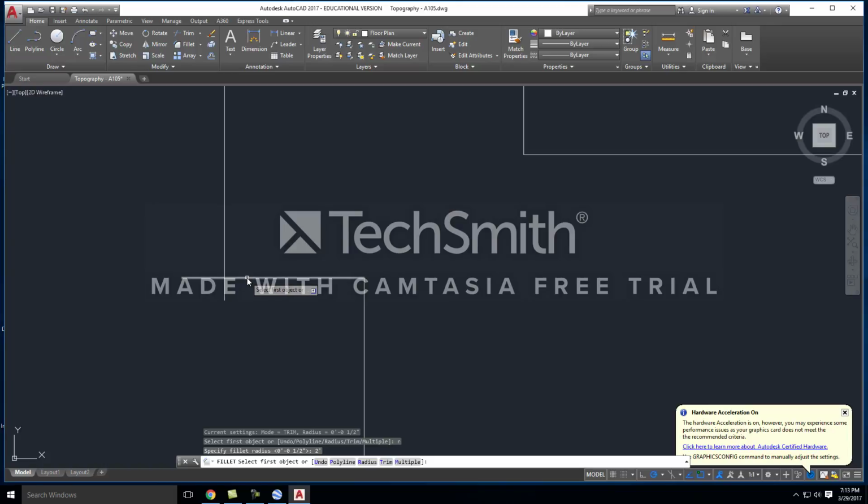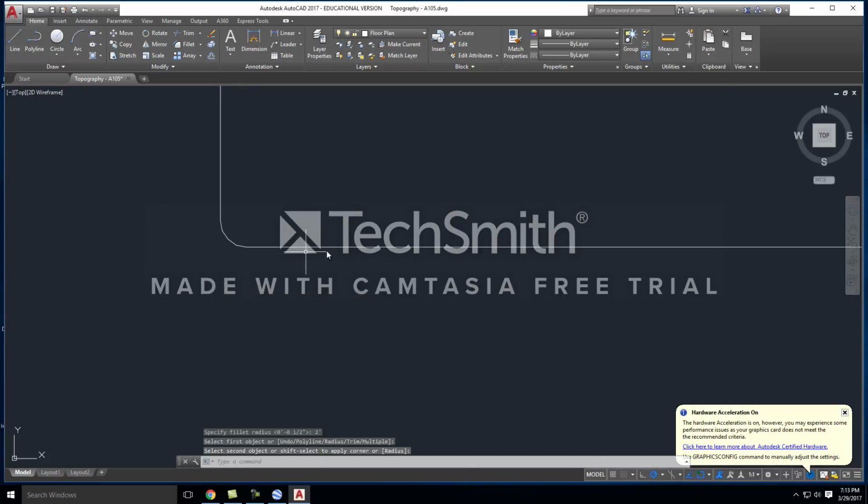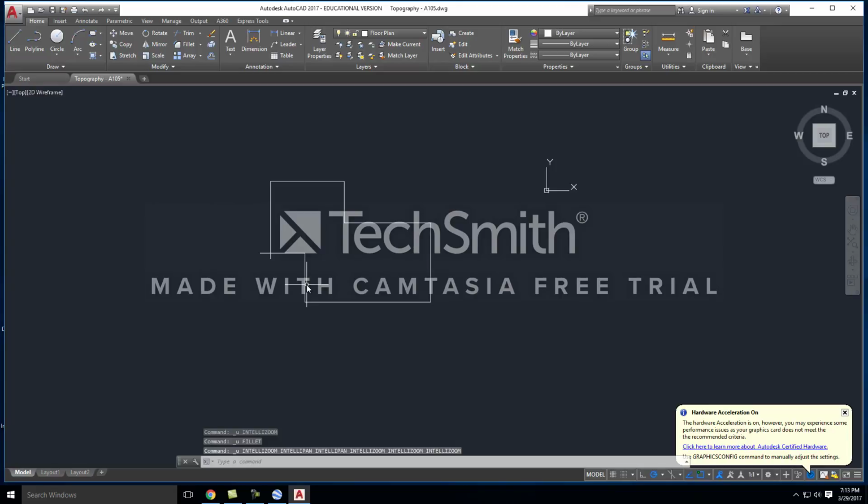Now it says to select the first object, and when I hover my mouse over the second object, you can see that it's actually creating that radius, okay? That's only 2 feet, so that's hardly noticeable. I actually didn't pay any attention to scale when I drew those original lines, but when I select that second line, it gives me a joined connection, but it also gives me a nice radius, okay? So I'll do that one more time.